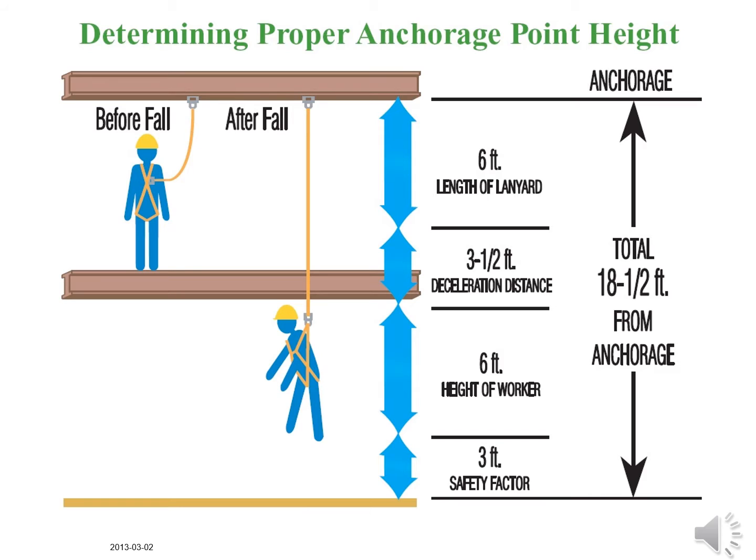Generally speaking, it is important to tie off as high above the worker's head as possible. Not only does that reduce the chances of striking the ground or other objects below him, it also limits the potential fall distance and the forces his body will experience in a fall. A high tie-off may even keep him close enough to his work area to allow for self-rescue if he falls.